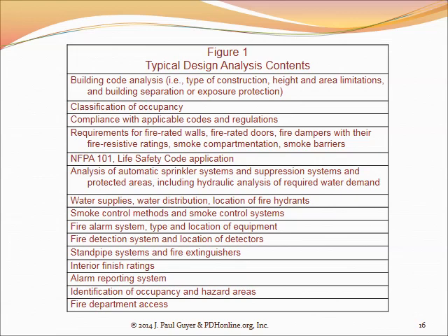To do that, you build barriers that permit some degree of isolation of the location where the fire takes place and keep that separate from the egress routes, how the people are going to be getting out of the building. You do this by constructing barriers, i.e. walls, floors, ceilings, and in different locations building them of different levels of fire-resistive construction. Anyway, these are all the items that you should include in your design analysis.